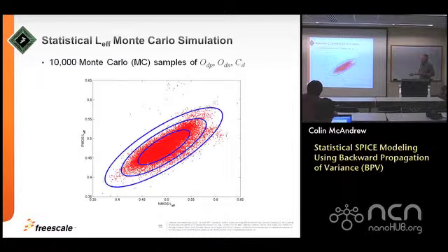So this is analytically calculated values for the ODP, ODN and CD using that matrix equation that I just showed you. I ran a 10,000 sample Monte Carlo, and these are the 1, 2 and 3 sigma yield ellipses that were then computed from that. So here what I've done is I've taken uncorrelated variables, and by mixing and matching them, I've made a model of the L effective variation that properly captures not just the distributions but the correlations.